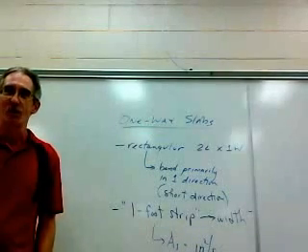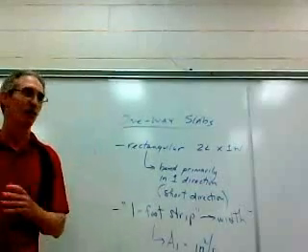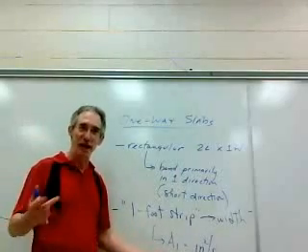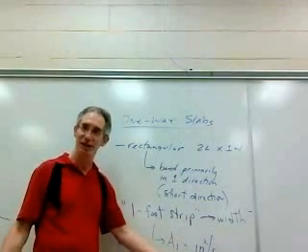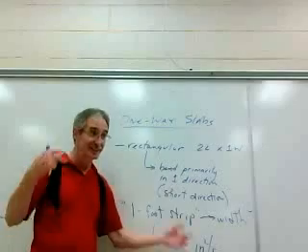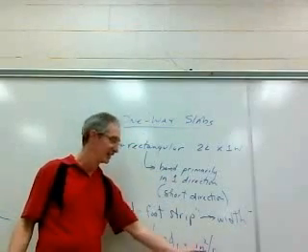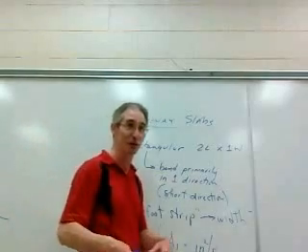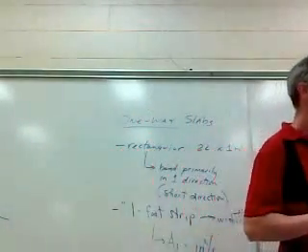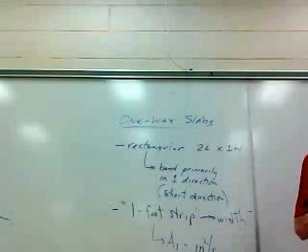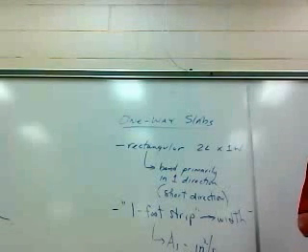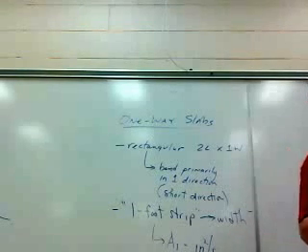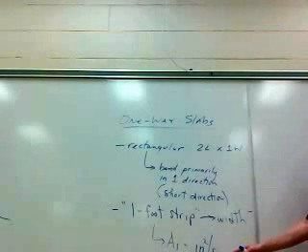The 1 foot concept is just our idea. But nonetheless, when we start looking at area of steel, since we are dealing with 1 foot width, the square inches that we deal with for the steel are, for design purposes, per foot area of steel. Okay? But out in the field, it's not that way. It's just a number 4 at 7.5 inches on center. Okay? So, anyway, does that make sense?